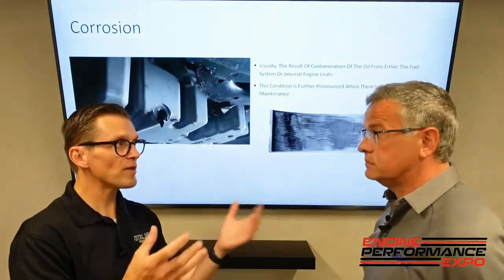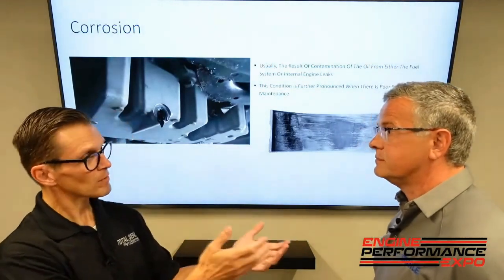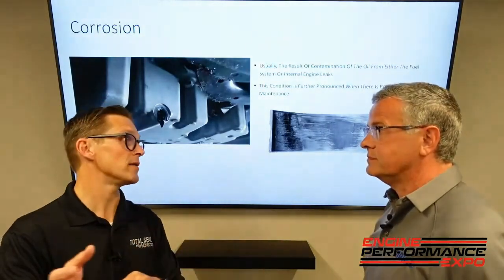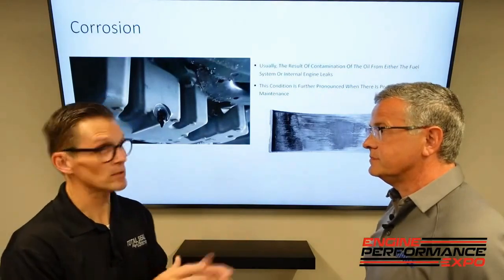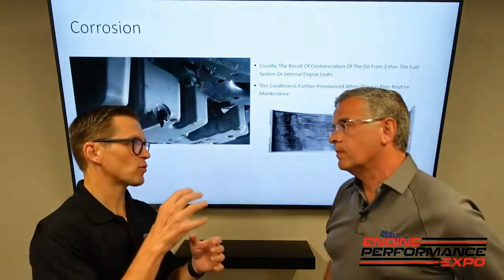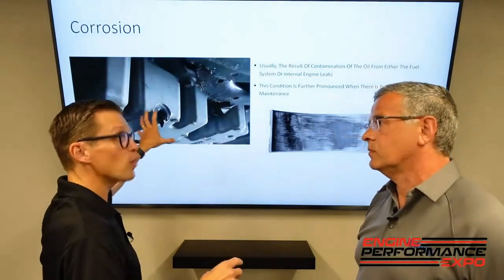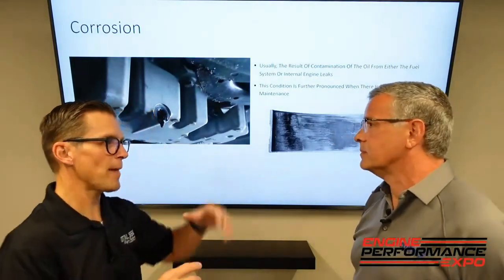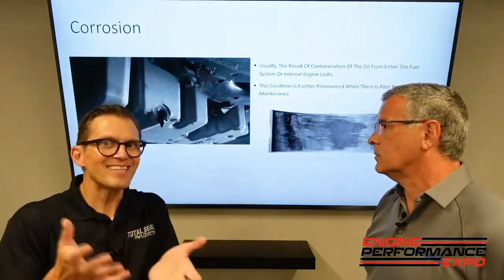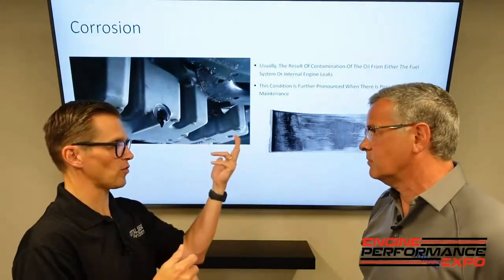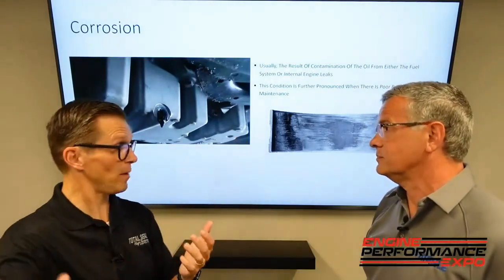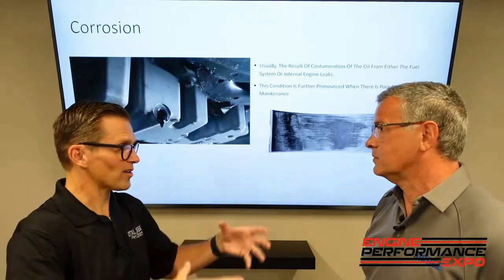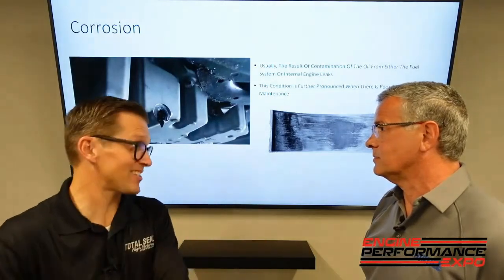In the old days, especially with diesels, there was a test that was really common in used oil analysis called TBN, total base number. Where that derived from was testing for corrosion wear, essentially. Because in a diesel, those heavy diesel fuels in the old days were high sulfur. Then you're making water with combustion. Water and sulfur together make sulfuric acid.